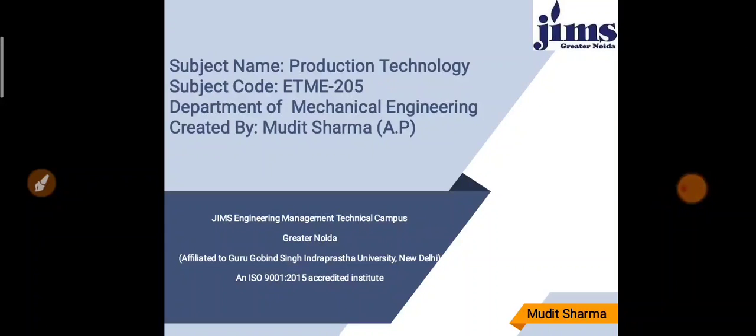Today, I am going to discuss the new topic, shell mold casting, or shell molding. First of all, before introducing shell molding, I am going to discuss some common applications where we can use shell mold casting, like making mechanical parts that require a high level of precision, gear housing, cylinder head, and connecting rod. These common parts of an engine will be produced with the help of shell molding. Shell molding is also widely used in producing high precision molding cores such as engine block and water jacket.